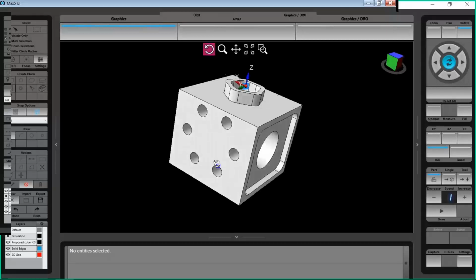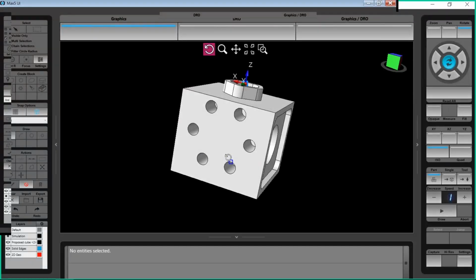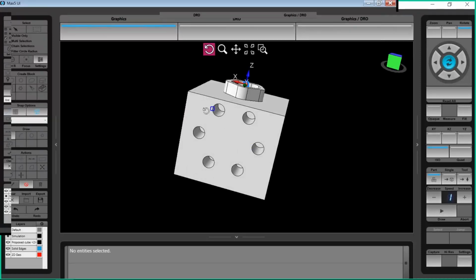That is more a limitation of the holes block itself. So if 3 of these holes had a different depth than the other 3, or let's just say these top 2 holes have a different depth than the bottom 4, that would have to be specified in a separate holes block.